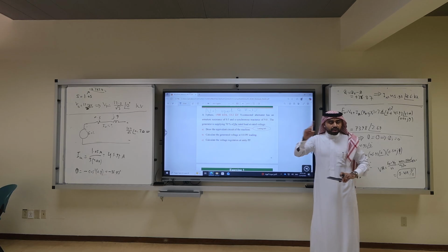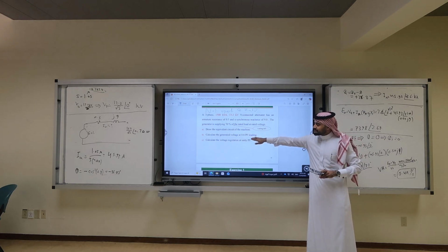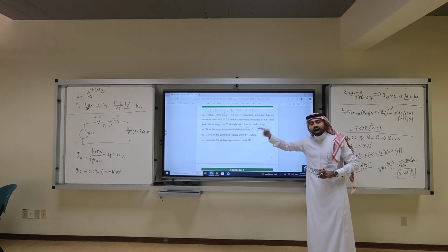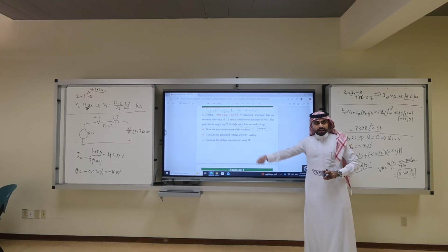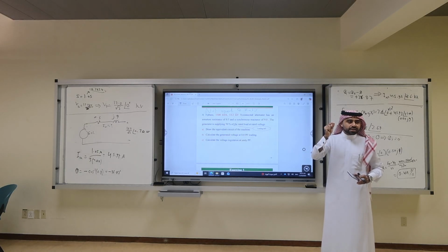So what is the trick? The trick in part B, he had a power factor leading. Part C, he wanted the VR for another unity power factor leading. So get the new angle of IA, get the new EA, get the new VR. Clear? Okay. So clearly, what is the most important factor that messes with the VR?